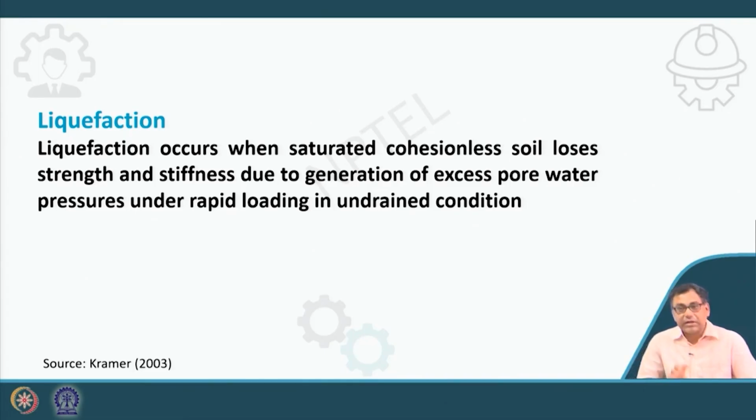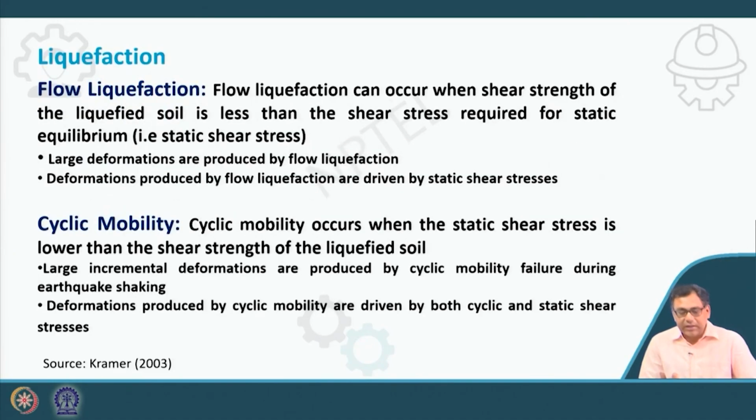Now, if the saturated cohesionless soil loses its strength and stiffness due to generation of excess pore pressure, then we can categorize liquefaction into two types. One is flow liquefaction, another is cyclic mobility. Flow liquefaction can occur when the shear strength of the liquefied soil is less than the shear stress required for static equilibrium, that is, the static shear stress.